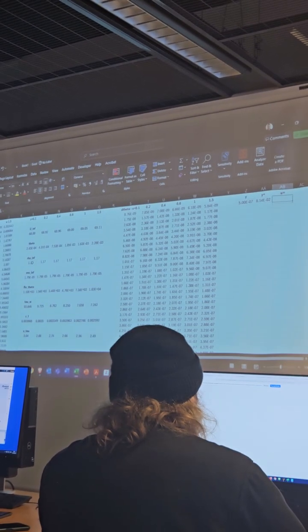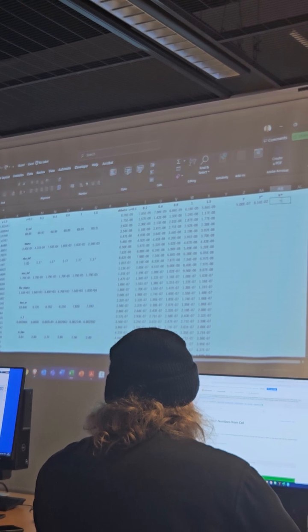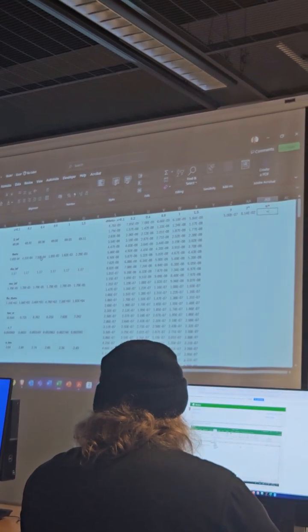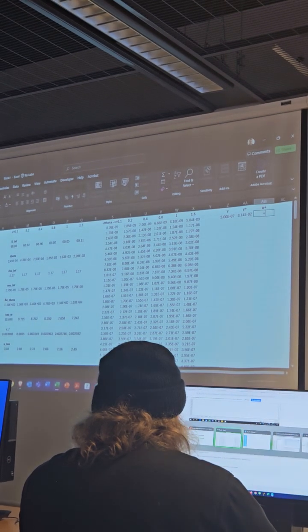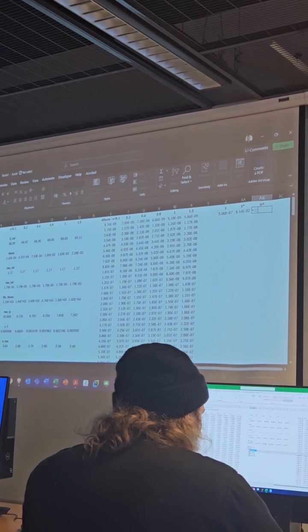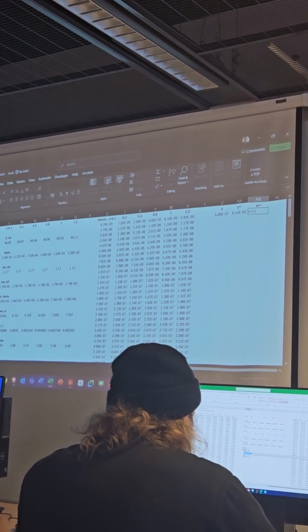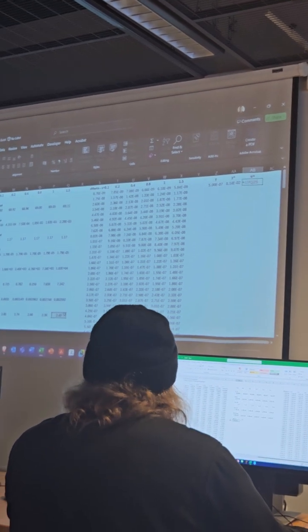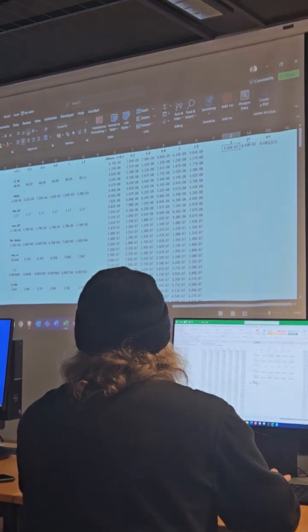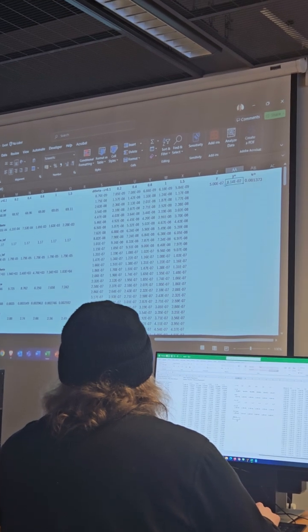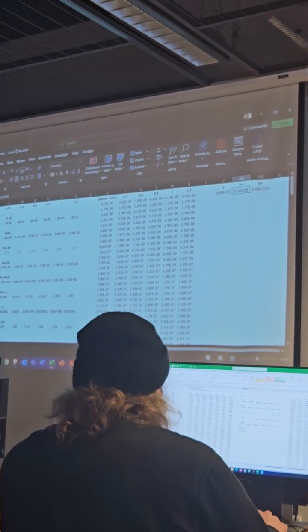Okay, and then finally we can calculate u plus. That is simply the ratio between the velocity at x equal to 1.5 over u tau. So we select this value of the velocity distribution here over u tau, the value of u tau at x equal to 1.5. Now, if you want to pull this along the different y values, we need to lock some cells.